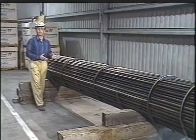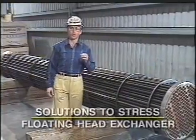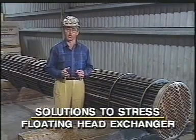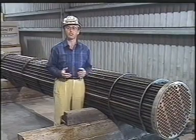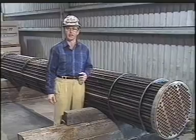A third type of exchanger is designed to allow both thermal expansion and easy maintenance. Because only one tube sheet is fixed while the other floats horizontally, this is called a floating head exchanger. The tubes are free to expand and contract in response to the temperature changes without stressing the joints, and the bundle and floating head can be removed for cleaning and inspection when necessary.